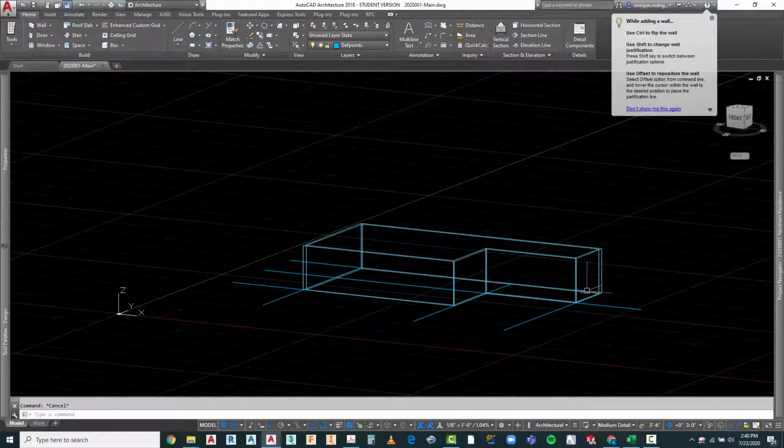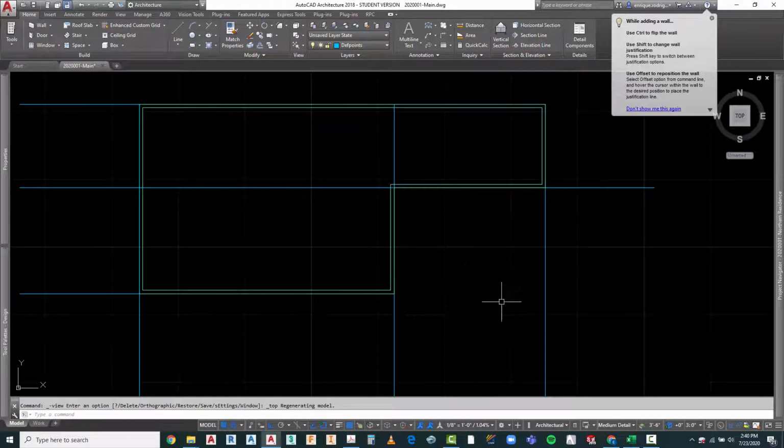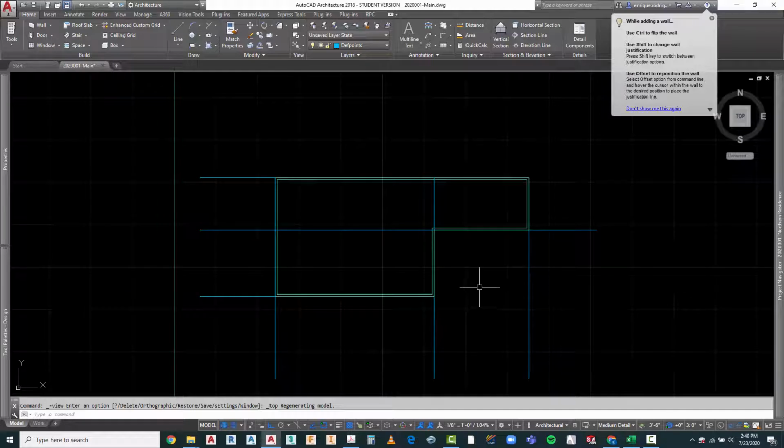If not, if any of these walls are down deeper, for example, we may modify that later on in the garage, you have potentially the problem of snapping down to the bottom of the wall that might be at -1 foot, etc. So for now, I want to make sure we have our walls located in the proper location, both horizontally, vertically, but also in terms of the Z-axis.